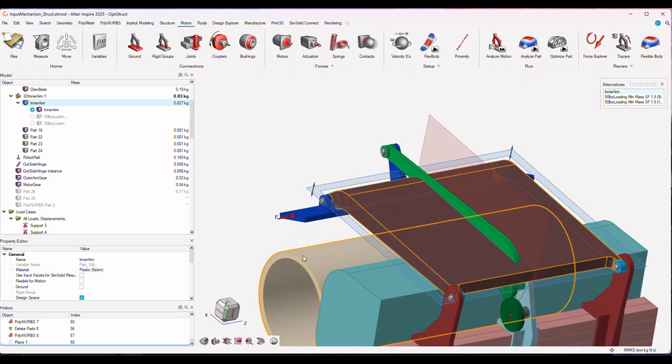And given the weight of this, we put that as a mass on the end of this, we can see how much acceleration is being driven. And that would be a target that we would put on the claw, right? The claw needs to hold that coral in with this amount of acceleration applied to it, which would be a force, right?